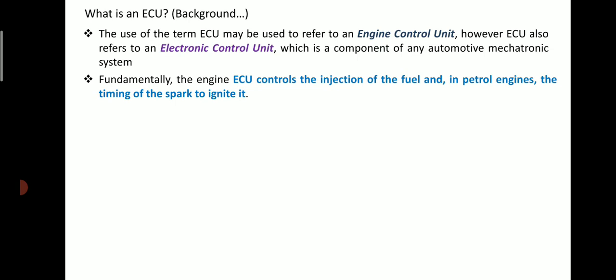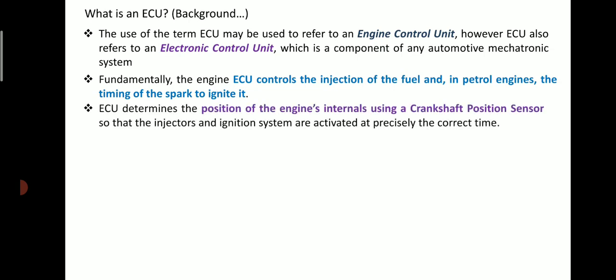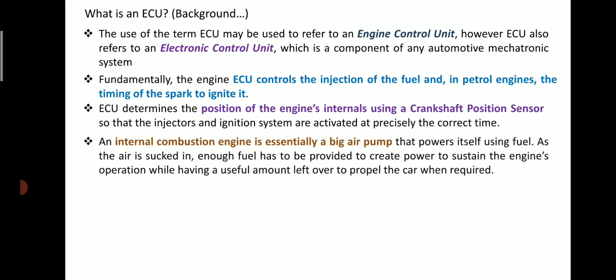Fundamentally, the ECU controls the injection of the fuel and, in petrol engines, the timing of the spark to ignite it. The ECU determines the position of the engine's internals using a crankshaft position sensor, so that the injectors and ignition system are activated at precisely the correct time.